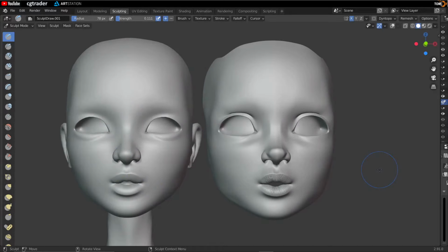The way we're doing this tutorial is a little bit backwards, because we're starting off with a low detail mesh and then creating a high detail sculpt. Normally, you'd create a high detail sculpt first and then create the low detail mesh afterwards. Either way, once you've got the two meshes, a low detail and a high detail, the process of baking the normals is the same thing. Okay, let's sculpt some details.